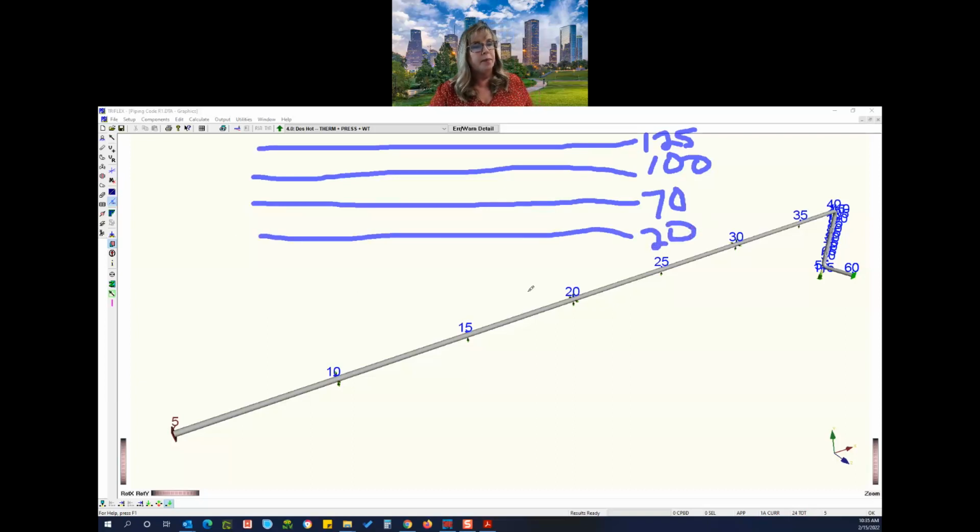The idea behind this is that the piping code, especially when you're considering the non-conservative allowables for displacement stress range stresses, will allow pipe to go from its elastic range into its plastic ranges. Once it gets into the plastic ranges, a percentage of the deformation can be permanent.